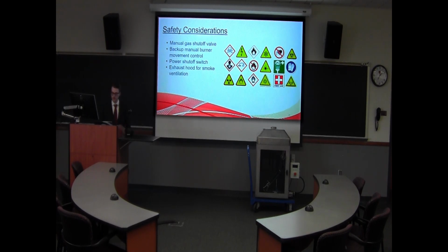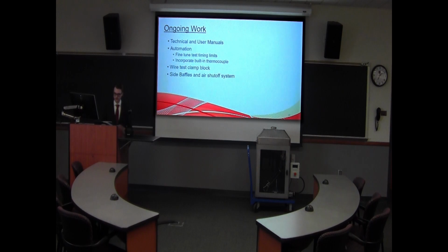Additionally, a power shutoff switch was integrated into the control panel, allowing the operator the ability to turn off the electrical supply to the entire cabinet, again, choking out the flame. If the automated movement system suffers a malfunction while a test was being conducted, a manual movement system was incorporated into the design so that the operator could move the burner away from the burning material to a safe location. Our smoke evacuation system will be capable of removing any hazardous fumes a sample might release during testing from the cabinet before the operator has a chance to inhale them.